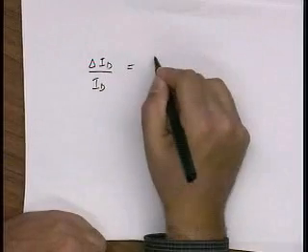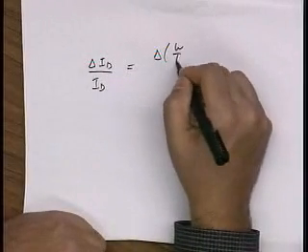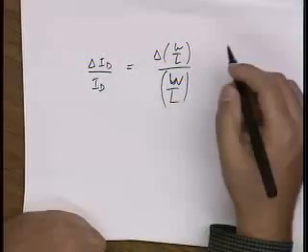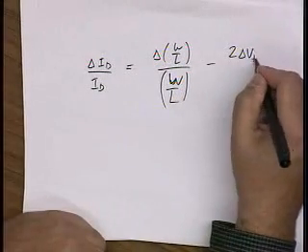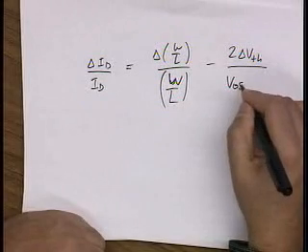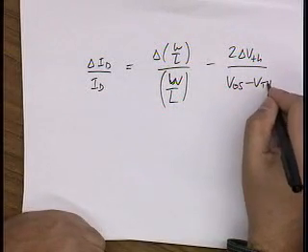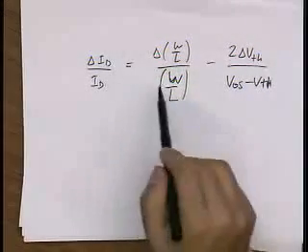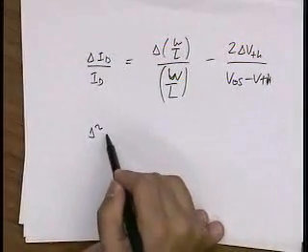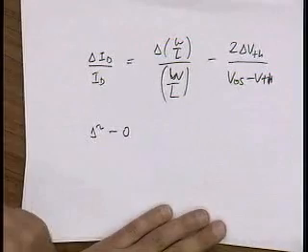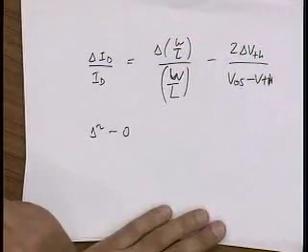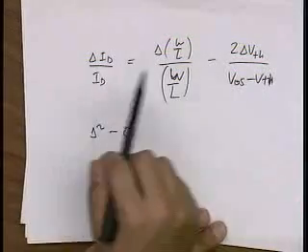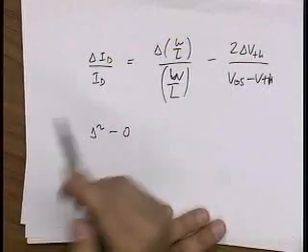When you derive this, the key thing that you need to do is neglect higher order terms, meaning any term like delta squared, you just assume it's approximately 0. You want to know the first order variation in the output current due to first order changes in WLs and VTs. Okay?